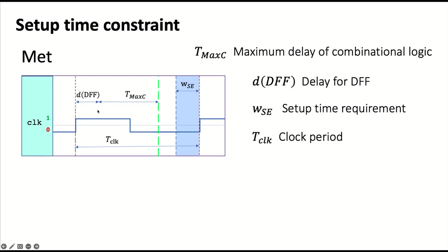Then that value possibly has to travel through the combinational cloud, through the logic, and that involves some delay. We did the static analysis where we can actually calculate when the output of a combinational network will have settled. And at this green line is when we know that the flip-flop input values are settled. This has to occur before the setup time starts at the next clock edge.